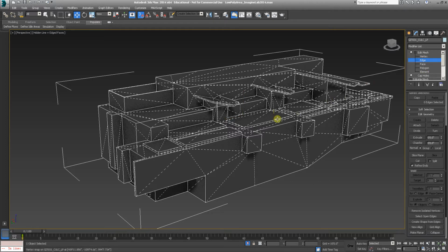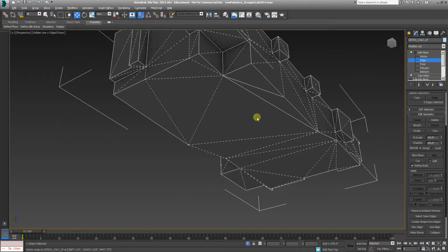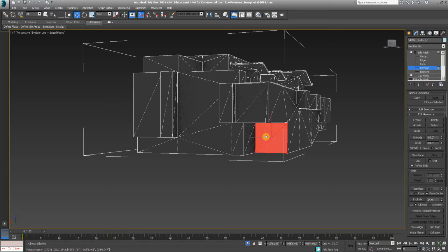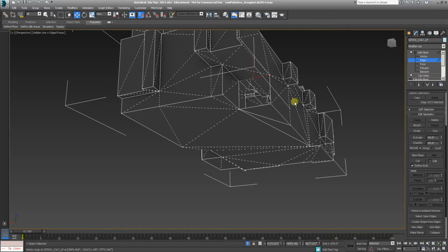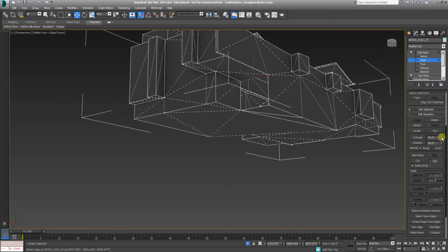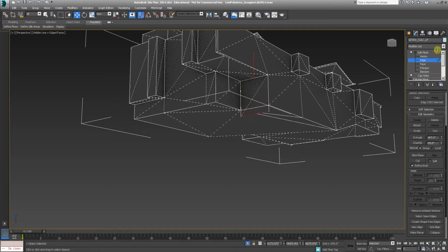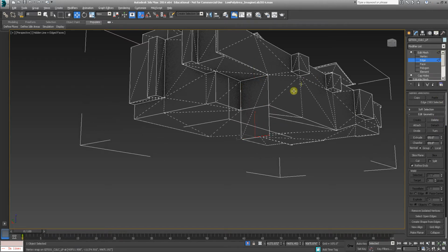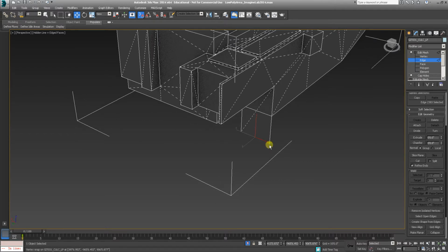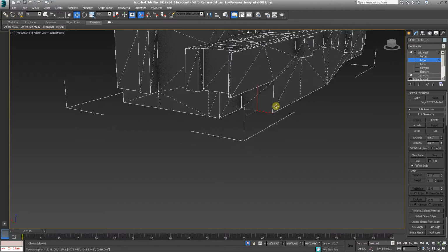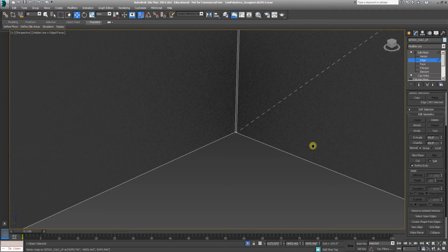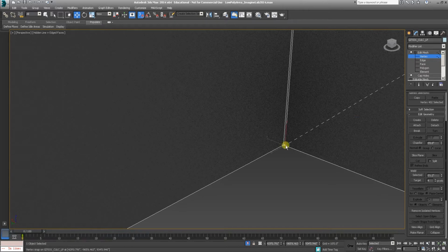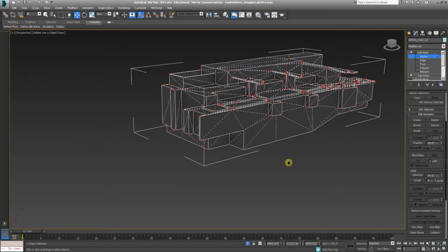There's a bunch of other ones. There's things where you can select an edge. If you've got a missing hole, let's say here, you can do things like select the edge and extrude it. So sometimes extrusions get a little crazy. So you can see I'm just dragging that spinner and moving it down. Sometimes I like to go further than I need to go so that I can precisely move and snap that back. And then a lot of times, if it's not totally planar, which is the case here, you can see there's a little bit of a gap there. You need to select that vertex and snap it in there. Select everything and weld it, and you should be good to go.